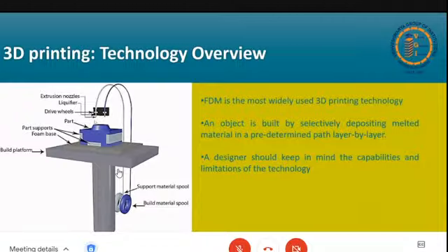So let us first think about it as a one nozzle system. In a one nozzle system, your wire will come up. There is a gear kind of thing, which can be attached at the bottom also or on the top, which will push or pull the material inside the nozzle.